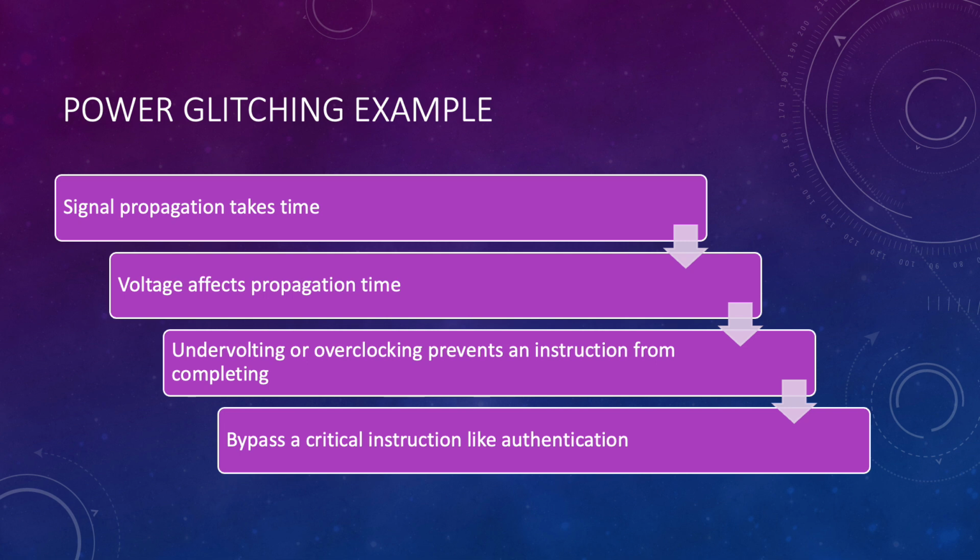If you were to try a clock glitching attack instead, you would try to increase the clock cycle fast enough to increment the program counter, but without giving enough time for the gates to settle, therefore skipping an instruction. These aren't the only ways to skip instructions, though. You can also use lasers, radiation, temperature, and other environmental factors to disturb a circuit.